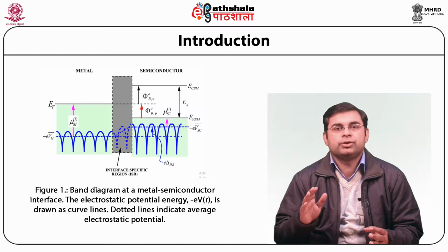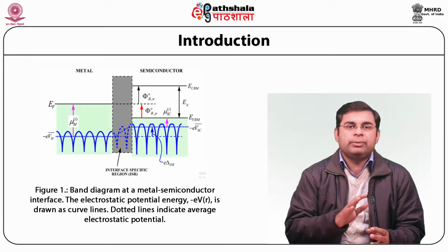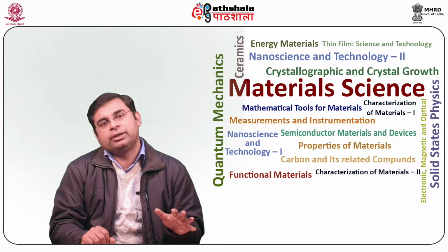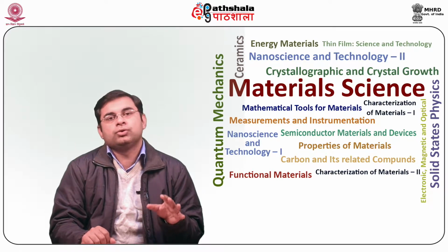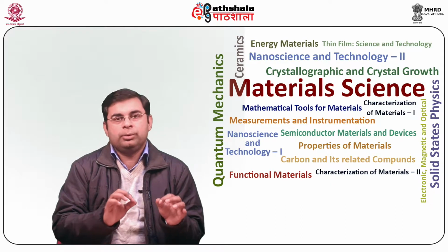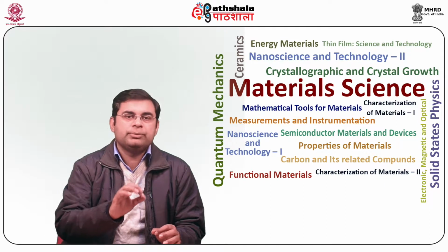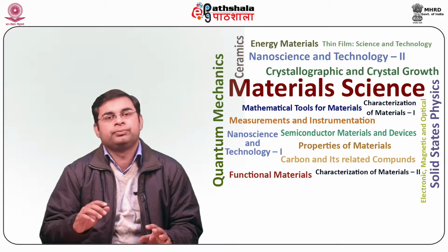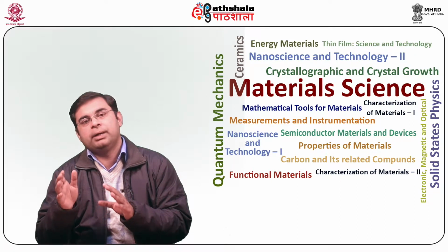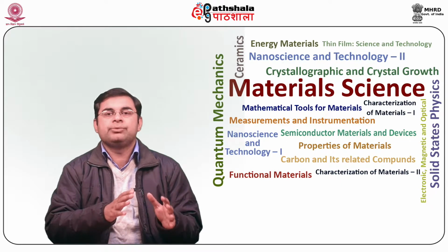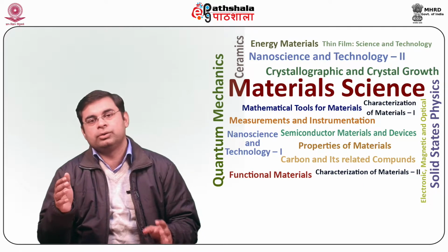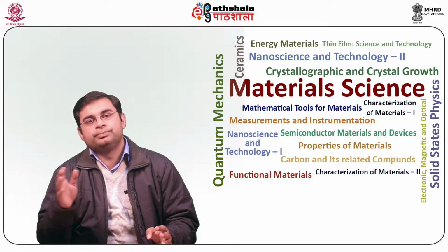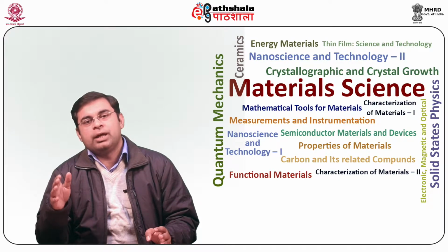The set of electronic states responsible for electrical conduction in the semiconductor depends on the type of doping of the semiconductor. In case of n-type semiconductor, the electrons present close to the conduction band minimum, that is CBM, contribute to the electrical conduction. Whereas in p-type semiconductors, the holes available near the valence band maximum, that is VBM, contribute to the electrical conduction. Because of the presence of the fundamental band gap, the lowest lying states for n-type semiconductor that can communicate with electrons in the metal are now at energy level phi Bn raised to power 0 above the Fermi level as shown in the figure.